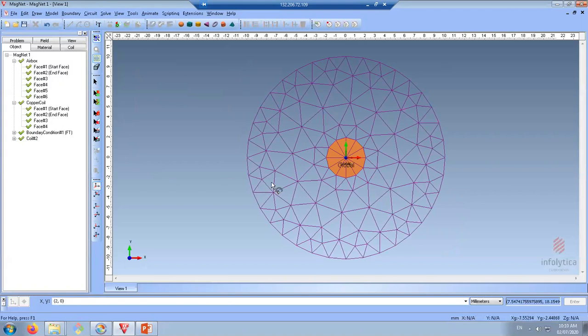I don't know if you're familiar with the finite element solver, but what it does in general is to fit some polynomial functions over these mesh elements and try to find the coefficients of those polynomial functions that fit the physics of the problem. And by physics, I mean the excitation, boundary condition, and things like that. So there's an iterative solver here which solves the equations of physics over these mesh elements iteratively until it converges to a stable point.